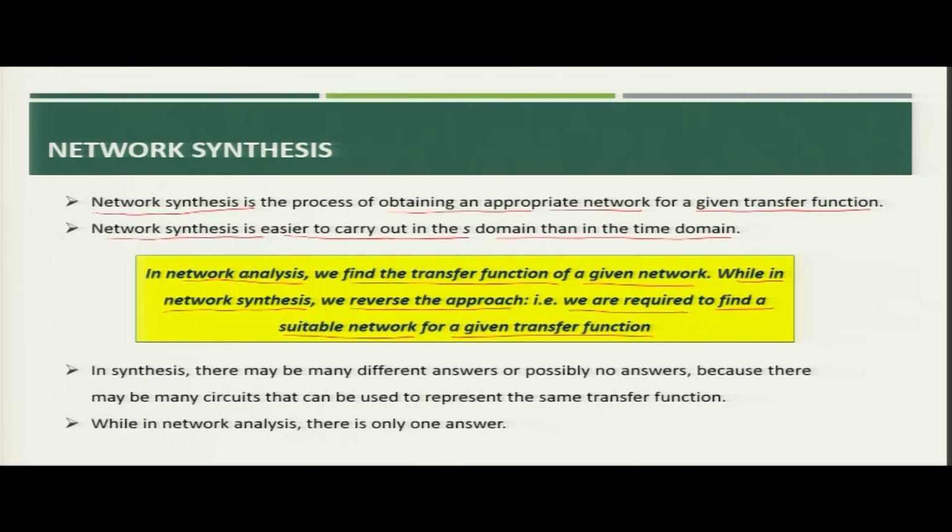So, in case of network synthesis, what will we do? We will get one transfer function, and from that we will try to find out the suitable network which satisfies the transfer function. Now, in network synthesis there may be many different answers, or possibly no answers, because there may be many circuits that can be used to represent the same transfer function.